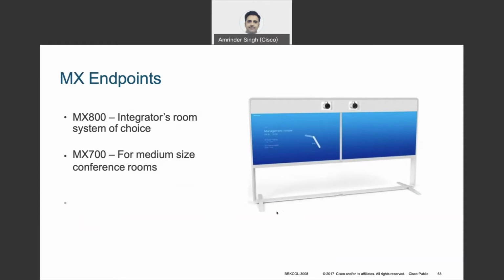On the left side, there is a panel. If you remove it, you have the actual codec installed right in front of this side. So if you need to do any cabling check, modify anything, or replace the codec itself, you just need to take off this panel. It's a magnetic panel, so no screws are included. Just remove it, pull it out. You'll see the codec. There's a screw on top and a screw at the bottom on each side. Just remove those screws and you can pull the codec out.